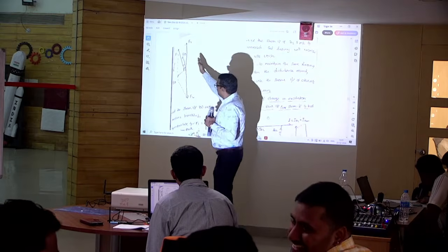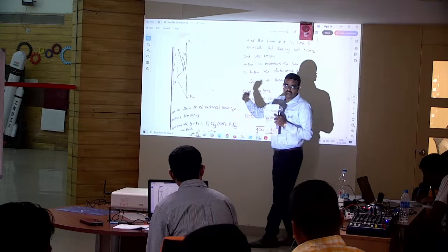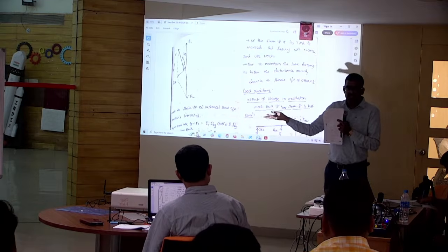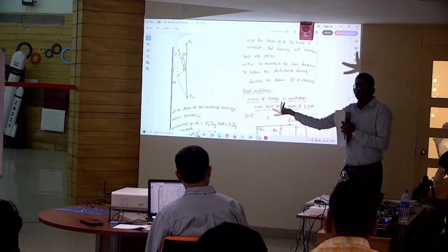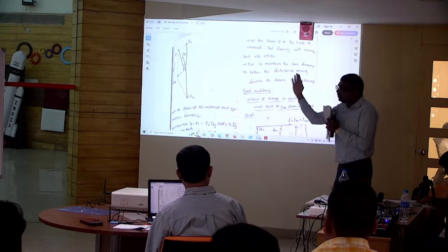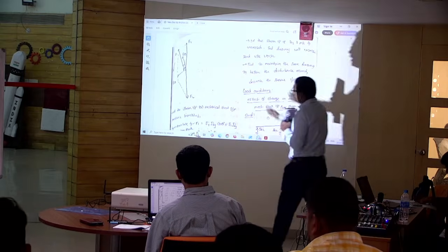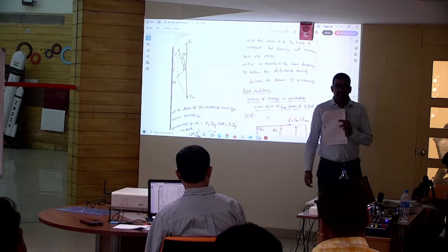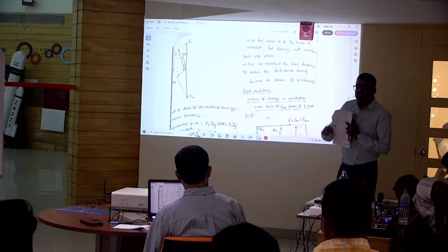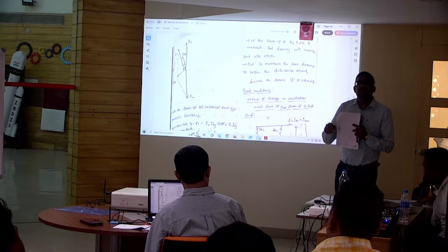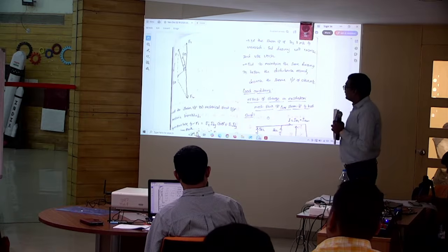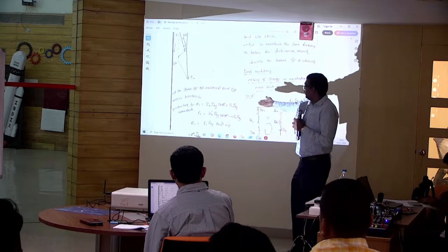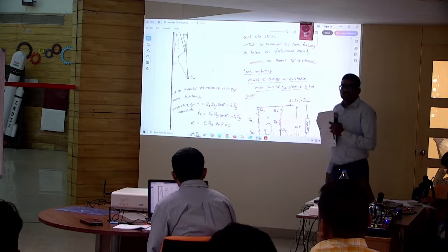Earlier, in this phase, E1 plus E2 must be 0. By KVL, if you write two voltage sources in parallel, to satisfy KVL, minus E1 plus E2 is equal to 0, that is, E1 is equal to E2. But now E1 has a phase relation. When E1 is shifted, we have a resultant EMF, a resultant voltage phasor. That is nothing but the synchronizing voltage, which is causing the synchronizing current. Look at the synchronizing current here. From that synchronizing current, what is the power?